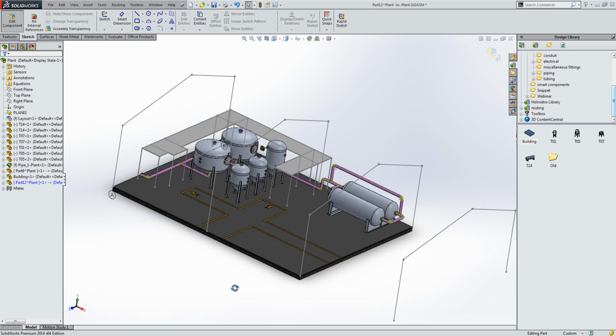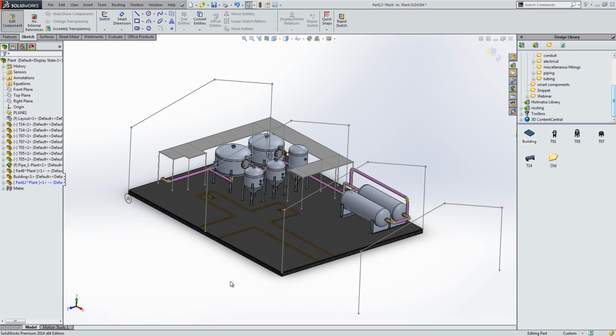for several buildings. Now, why would you use a grid structure rather than drawing it yourself many times or doing a pattern of features? Well, the grid system is a very easy way for somebody to define how a building is laid out, and enables you and the architect and the customer, who may all be working in different software packages, to use the same grid system and keep things up to date, because you can come back in and edit these. Now these sketches are here, however, what we can do is start to add a weldment along them.